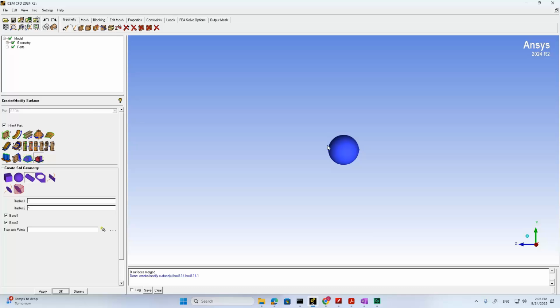The velocity only changes in a very thin layer close to the body surface called boundary layer. And away from this boundary layer, the fluid flow is pretty much a uniform flow. It just flows with the same speed, same direction. Not very interesting. I'm not saying it's not important, but definitely not as important as the boundary layer, right?